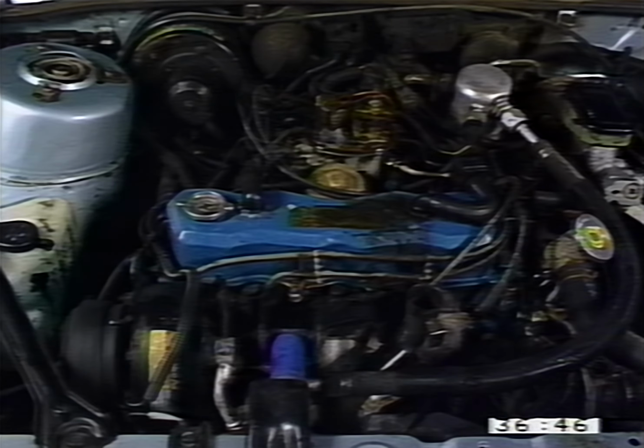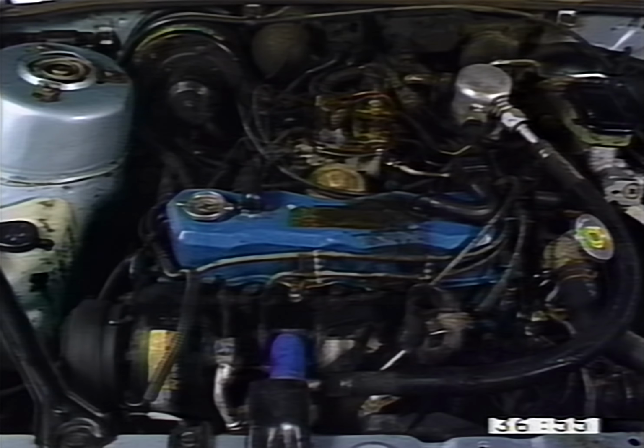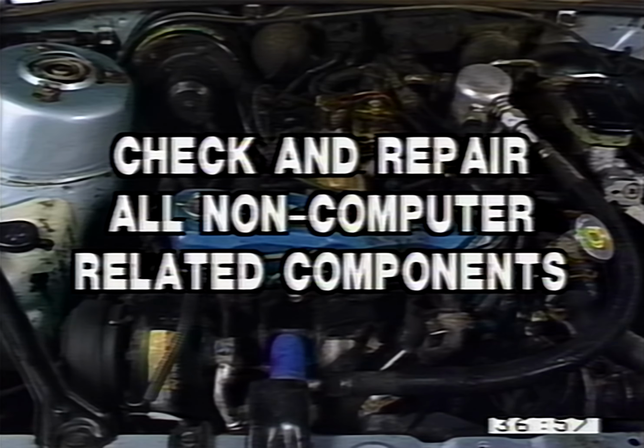Computerized engine control systems are diagnosed in this order. Make sure that all engine systems not associated to the computer are functioning to specs. Now don't continue testing unless all non-computer related problems you find are functioning or have been repaired if faulty.